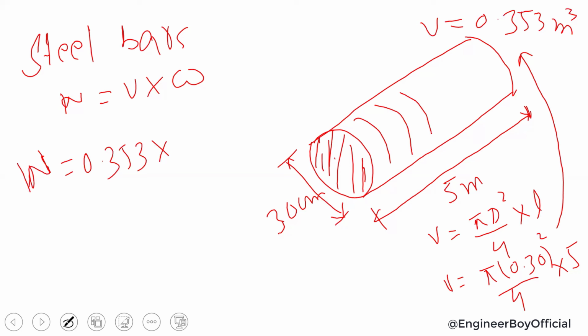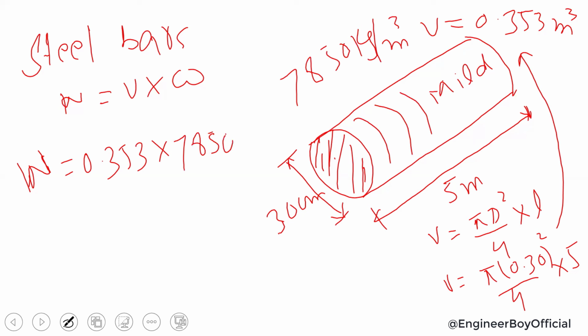However, in construction projects, most of the time we use mild steel, maybe in slabs, in beams, in columns. So these are normally mild steels. Now, the weight of mild steel is 7,850 kgs per cubic meter, if you remember this. So you have to put that value over here. Again, you have to Google the unit weight of each material. So the process is just simple for you.